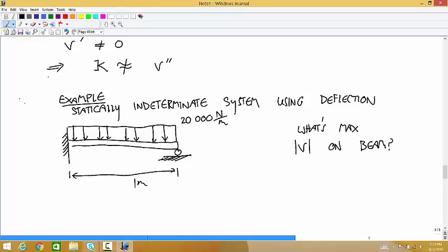So we're going to have to represent those external loads using variables and then go all the way through, calculate the deflection, and require that the deflection is equal to 0 at the right end, and that the deflection and the slope of the deflection are equal to 0 at the left end, and use that to calculate those external loads. Any questions about the flow of this problem?